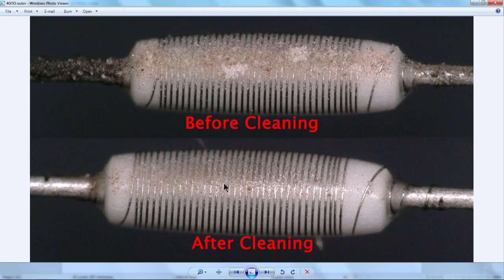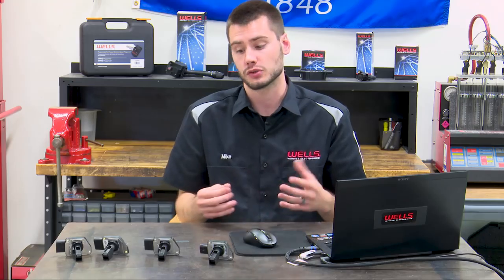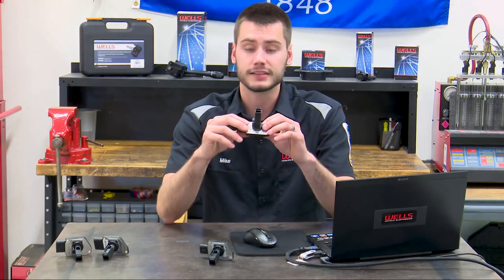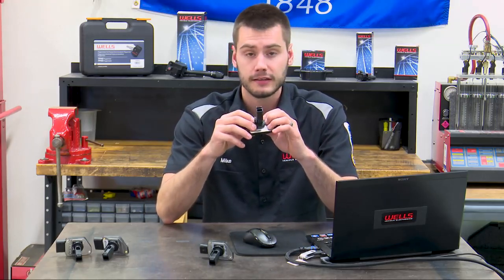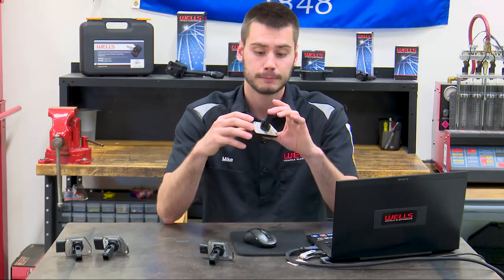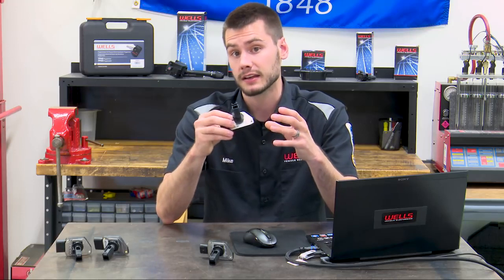So long story short, is cleaning of the mass airflow sensor worth it? I could put this in the vehicle. It would probably work today. Is it going to work 100%? Are we going to hit that 99% load? Are we going to hit that 185 grams per second? I don't know. Maybe today.